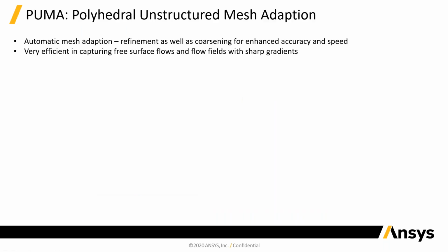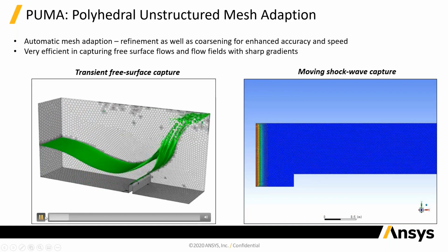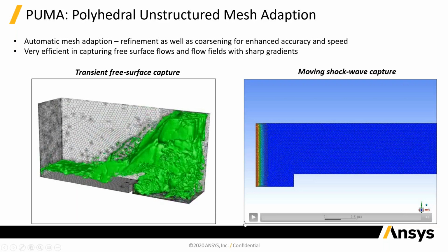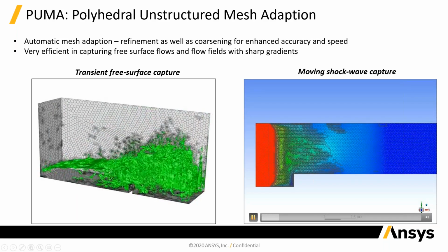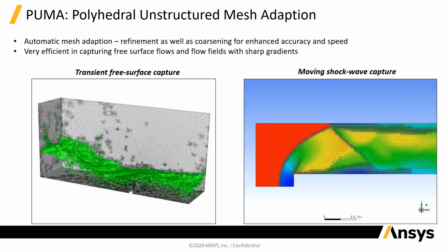Academics think of mesh refinement as start off with a mesh size of 2, then make it 1, then make it a half, and very quickly you realize that that's not something you can ever do out in industry. What you're actually going to do is put your mesh where you need it. And there's huge amounts of work going on to do mesh adaption, and not only for steady flows, but as you can see, for highly transient flows.